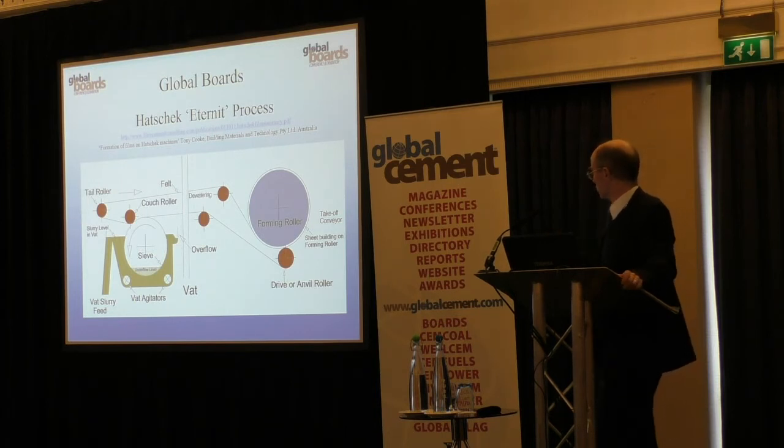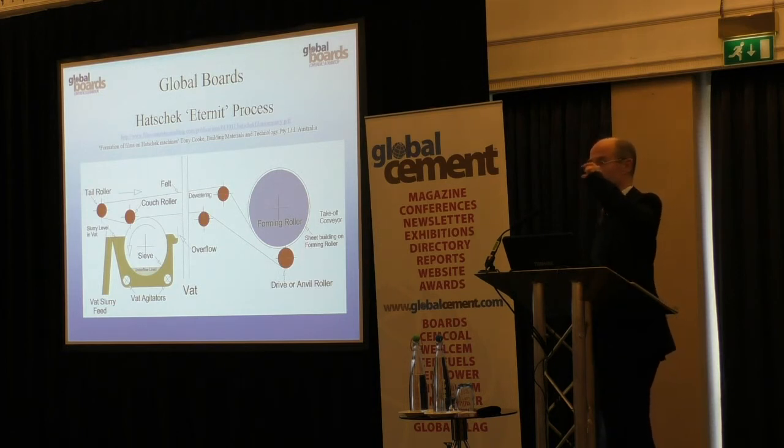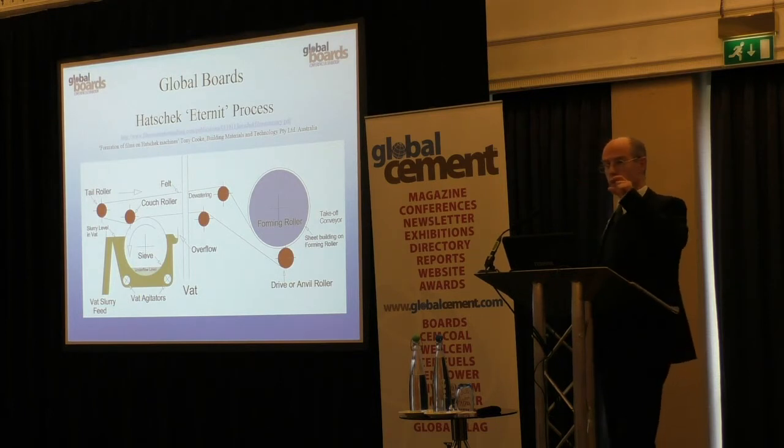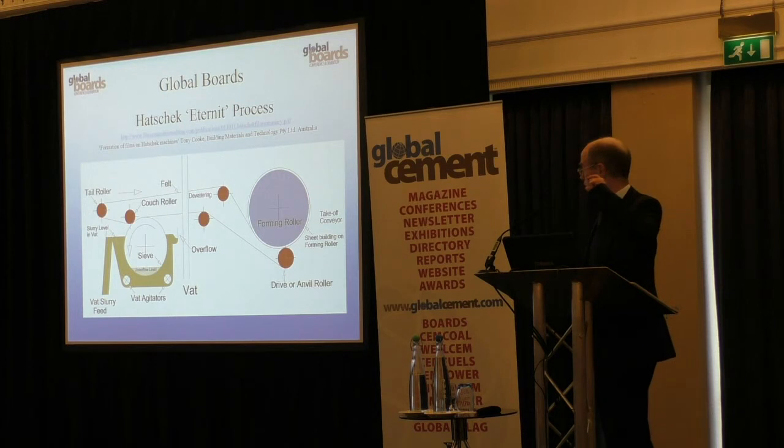A little bit further, and then there's a process of a forming roller where the fibre cement sheet, very, very thin, will be transferred to the forming roller, which rotates continually like this, and it essentially builds up a thicker layer of fibre cement sheets, a number of fibre cement sheets, until the desired thickness is attained.